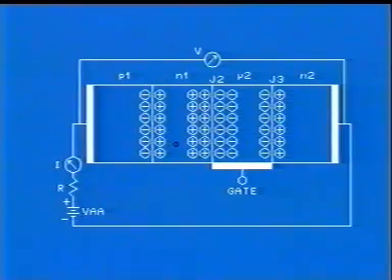On reaching N1, it temporarily increases further the bias on J1, thus causing three holes to cross over from P1 to N1. Again, two of them cross over to P2 and increase bias on J3.